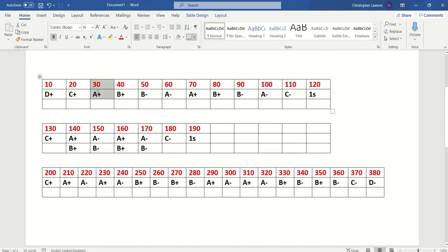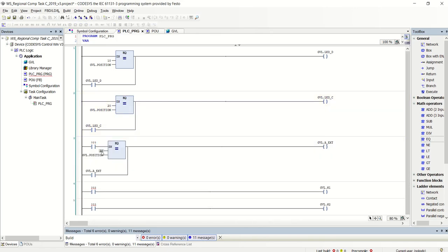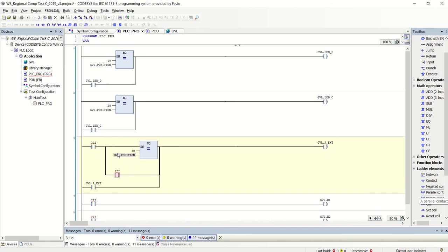Right, now look at A. A comes forward in step 30, and it also comes forward in step 70. So 30 and 70 needs to go in there. So put that down here, pop in 30, and we got to do an OR. Okay, so you need to get that kind of parallel context set up.